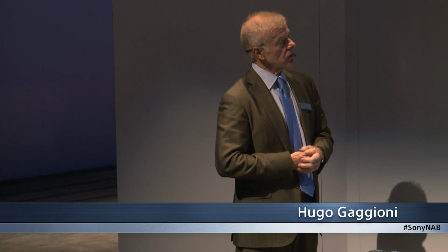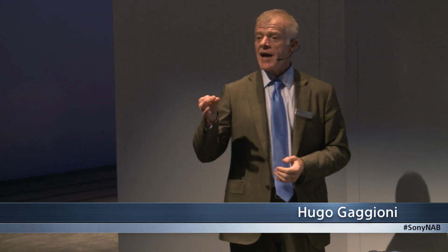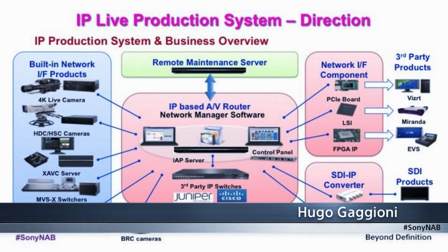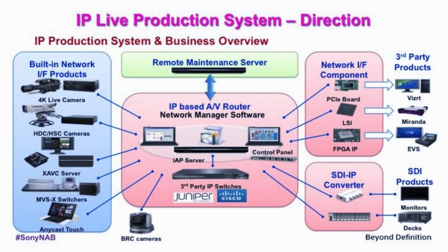This is our dream. Our direction is to, in the near future, begin implementing IP packet transmission directly from our studio cameras, monitors, servers, switchers, and the like, and in the not very distant future, you are going to see RJ45 connectors side by side with BNC connectors. These IP packets will be streams of packets. There is a need for network management software to provide the quality of service of the entire infrastructure. For those devices that cannot be retrofitted right away or easily, we will have small boxes that convert IP to HD-SDI or HD-SDI to IP. These are going to be portable conversion boxes.